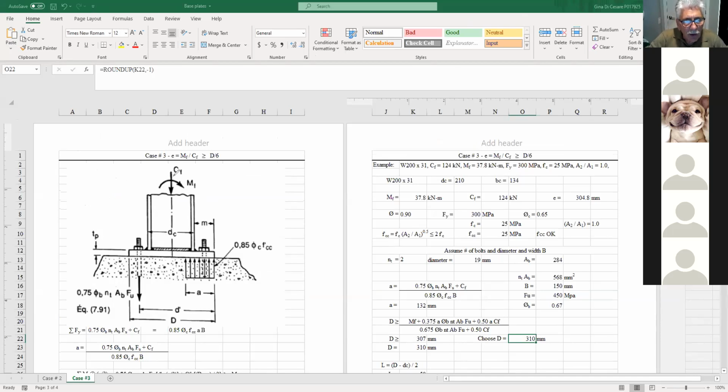So basically, when you have a bending moment here, one side is in compression and the other side is in tension. Therefore, it can happen that this bending moment is so high that the plate doesn't even want to touch the concrete anymore. It actually wants to lift off the concrete. And therefore, anything that you use here to calculate the bearing resistance of concrete doesn't provide any bearing resistance, so what's really happening is only part of the concrete is offering some bearing resistance, and that's what these formulas do. Now, when you look at this type of situation, there are two situations.